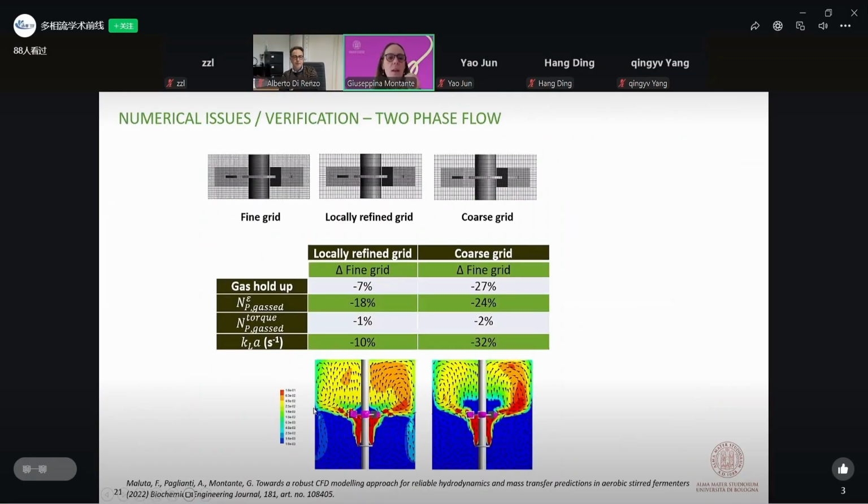But of course, the most reliable way and the most complete way is by population balance modeling. It is very computationally intensive, going to population balance. And so just a word to say that we have to be aware of the importance of having a mesh in the two-phase flow that is fine enough.